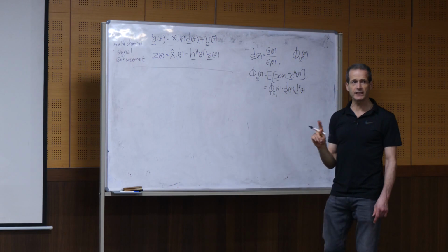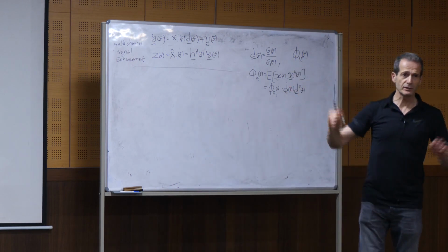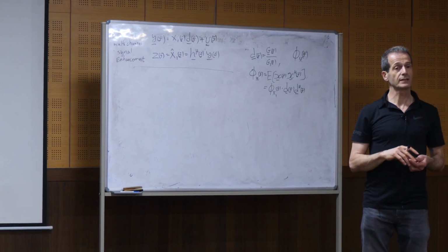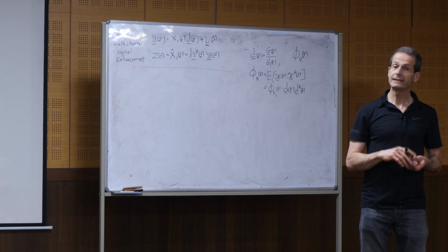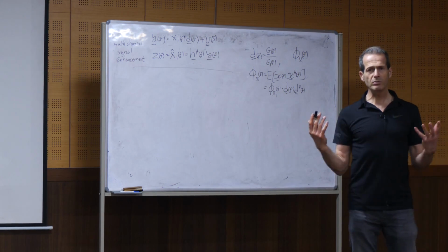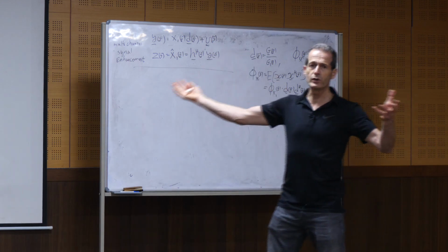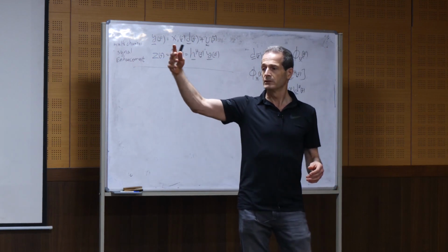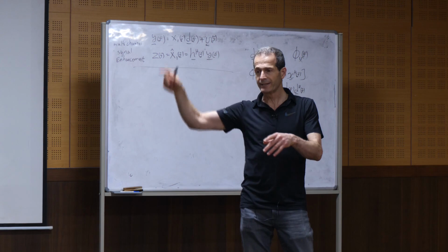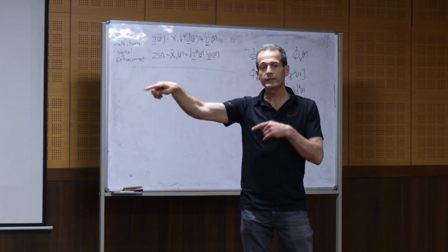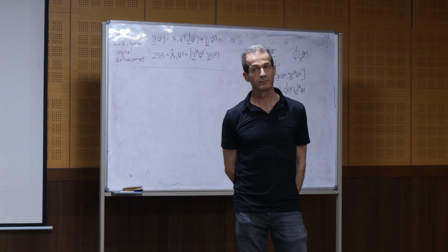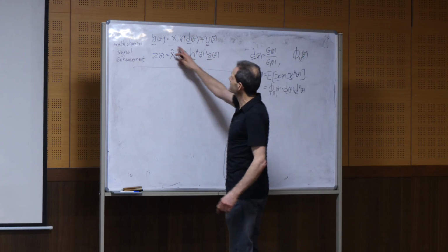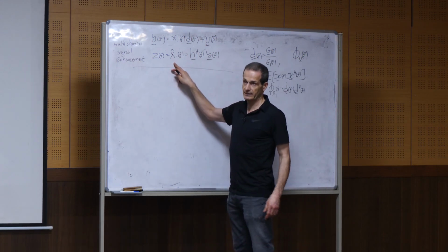So I know the correlation of the noise components in every two sensors, the correlation between any pair of sensors, which means that I know the environment, the background noise in the environment. Using the sensor array, I know how they correlate between two sensors. So this enabled me to obtain an estimate of the desired signal in the reference sensor.